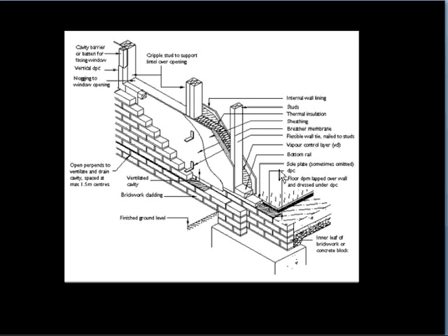In terms of thermal performance, the space between the studs is filled with insulation, and if you want extra performance we can widen the gap. Perhaps instead of using rectangular section timber, we can use I-section timber, and we can also put insulation on the outside of the frame as well, a warm frame construction.